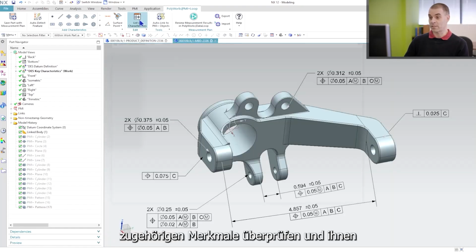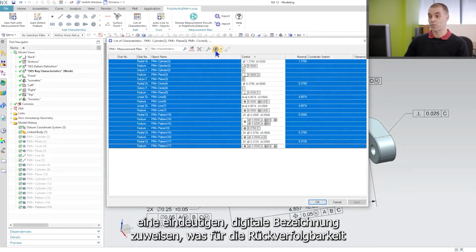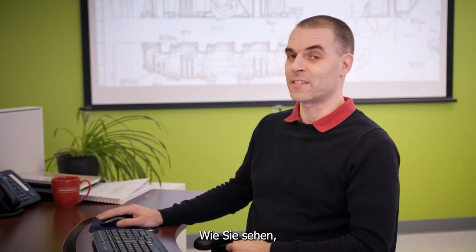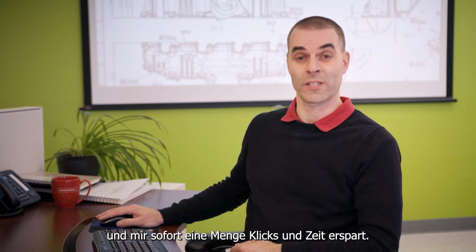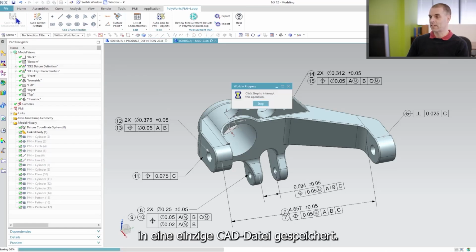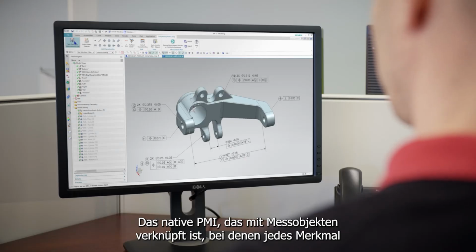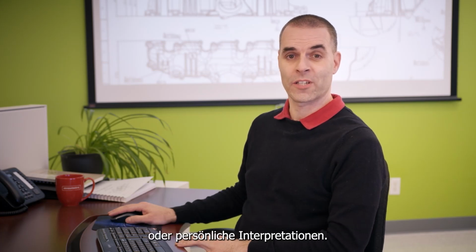And I can review the associated characteristics and assign them a digital unique identifier, which is critical for traceability purposes. As you can see, it is a one-click operation that identifies all the selected characteristics almost instantly, saving me a lot of clicks and a massive amount of time. Finally, saving the part with the PMI+Loop control plan embeds in a single CAD file the native PMI associated with measurement objects where each characteristic is uniquely identified, leaving no room for assumptions or personal interpretation downstream.